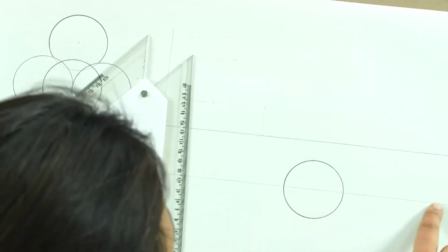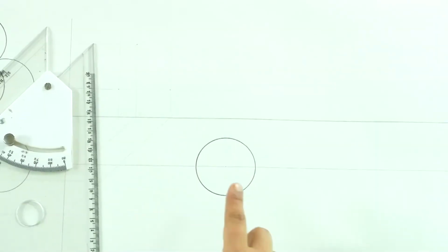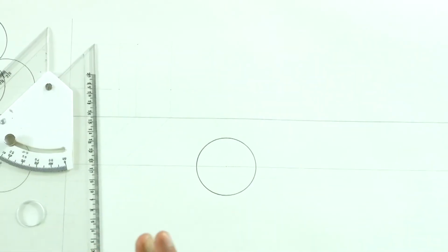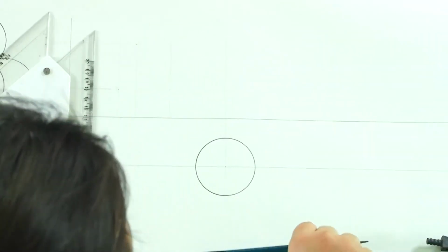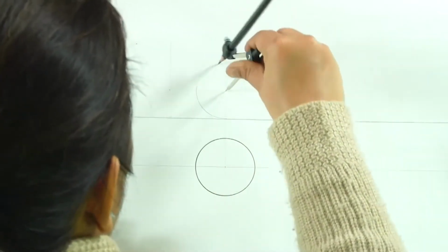We have a bigger sphere which is kept in the same line as this. So, the line which is connecting these two spheres is actually parallel to VP, but it will not remain parallel to HP, because the bigger sphere, the center of it will lie slightly higher. So, what we will do? We will make again, and we are assuming that both these spheres are resting on the ground.